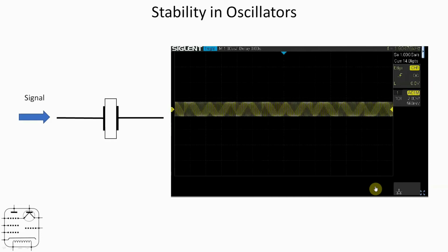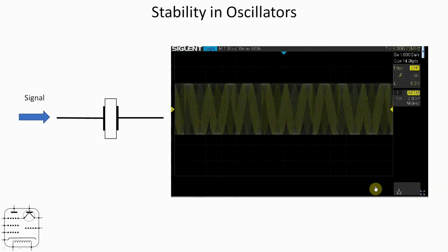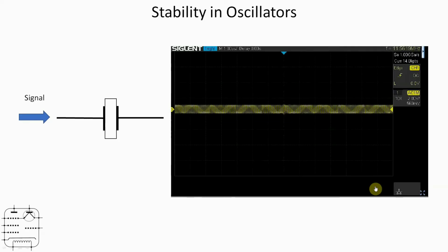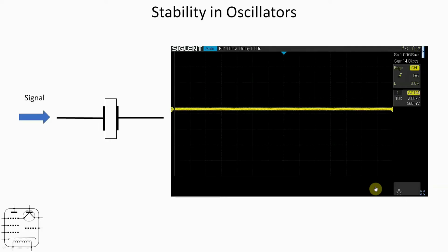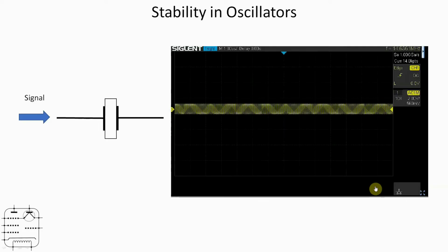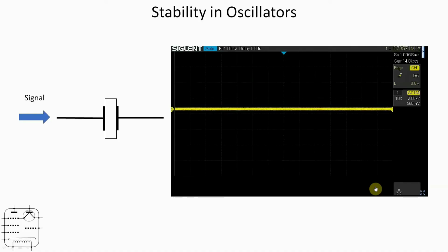Now I'm just using the screen grab function here, but you can see how that signal level, as I sweep backwards and forwards, increases and decreases quite markedly, and that's as we pass the point of resonance. Now my scope's a bit of a blunt instrument for looking at the exact frequency that's going on here, but what we can do is the same thing on a spectrum analyzer.